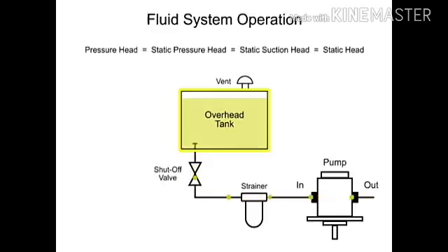reservoir is placed at a height higher than the center line of the pump and is the measure of distance from the pump to the tank. This creates a positive inlet pressure and helps fluid flow to the pump.